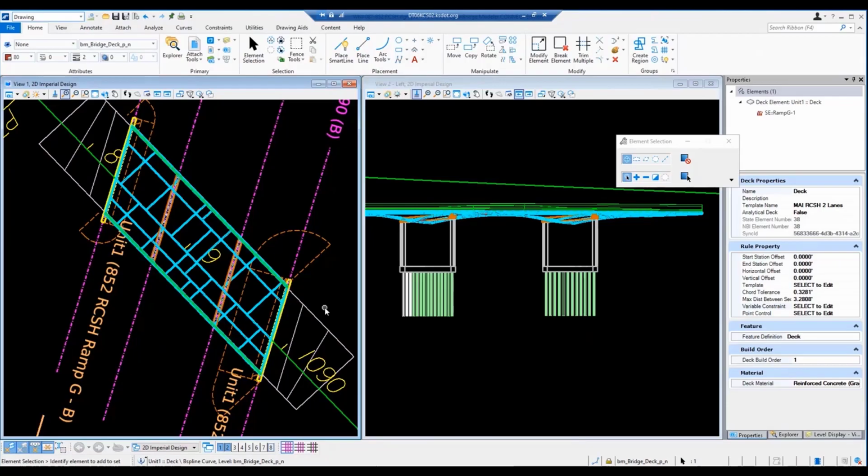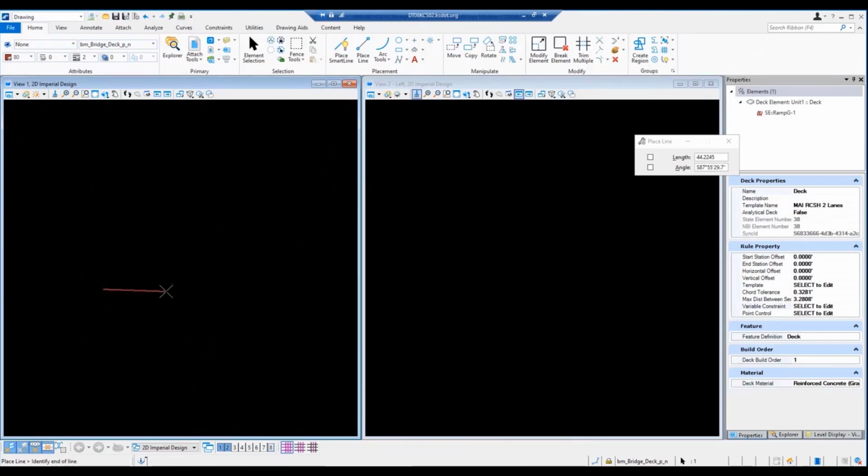You can extrude that corral rail portion of it, no problem, since the end post thickness is equal to the thickness of the corral rail. They're 1 foot, but then all the interior posts are 10-inch width. I am very curious if you could do the same thing that Stantec did with the haunch slab, defining a square wave. You would define an extrude template that was 10 inches wide.